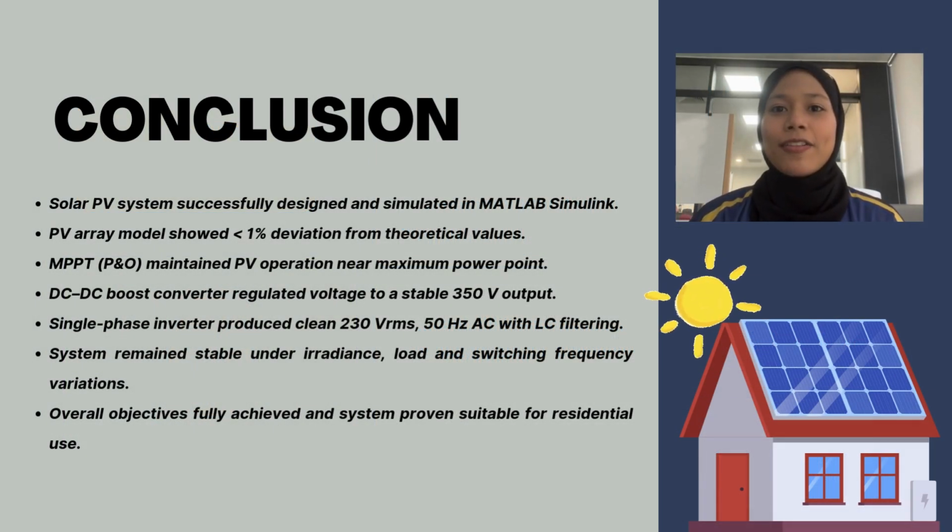In conclusion, our solar photovoltaic system was successfully designed and simulated in MATLAB Simulink, and all project objectives were achieved. The PV array model showed less than 1% deviation from theoretical values, confirming accurate modeling under different conditions. The DC-DC boost converter, together with the MPPT controller, operates effectively, maintaining the PV voltage near its maximum power point and delivering a stable 350 volt output.